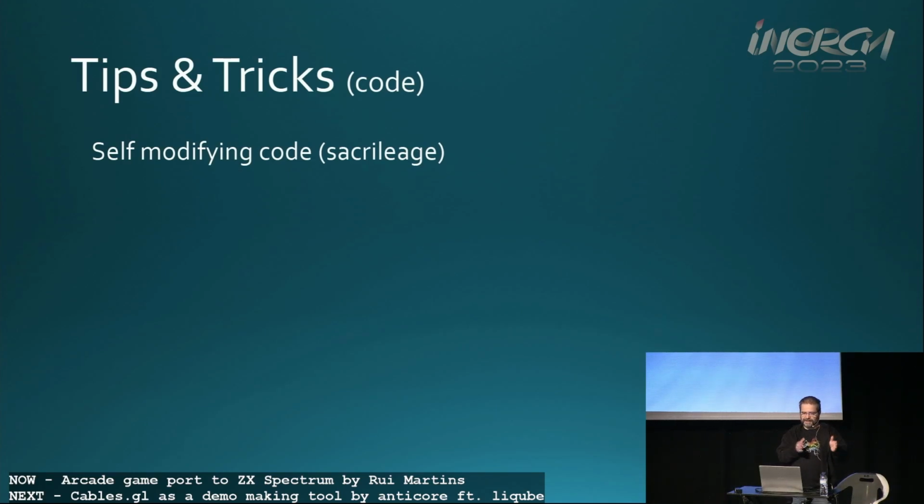But if that value is similar to a constant within the loop, we can overwrite the value in the instruction itself, and instead of loading from memory, we load BC with a specific value. And the difference is that that instruction, for example, will take 10 T-states, which is half of the other one.